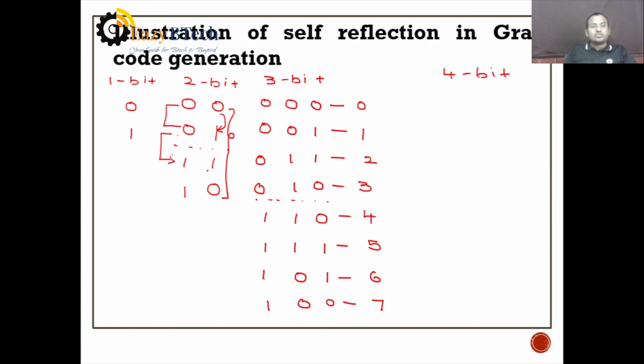You take the next two successive code words. Now these MSB bits are as it is, so the LSB is changed from 1 to 0. So any two successive code words you take in the gray code, they differ in only 1 bit position. So we can easily identify if any error occurs while transmitting from one place to another place. Similarly, you can observe in the 3 bit gray code also. You take any two successive code words.